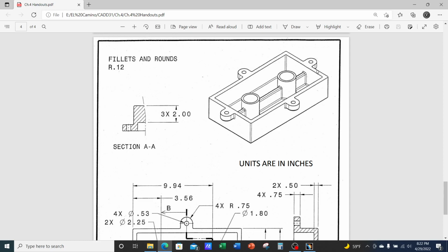We're first going to create a rectangular sketch for the main body. And then we're going to bring in the ribs, these 3 ribs. That'll be our second operation, the 3 ribs. And our third operation will be to create these shafts. And then our fourth operation will be to create holes in the shafts. And finally, we'll do the tabs on the outside with the holes.